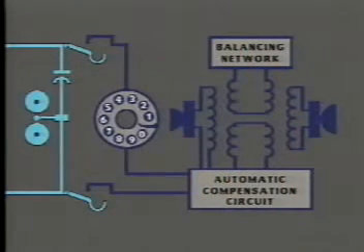In other words, alternating current flowing through the coil magnetizes the steel core. Being metal, the clapper is then repeatedly attracted to and repelled by this magnetism, striking the bells in the process. Typically, the ringing voltage is about 90 volts.